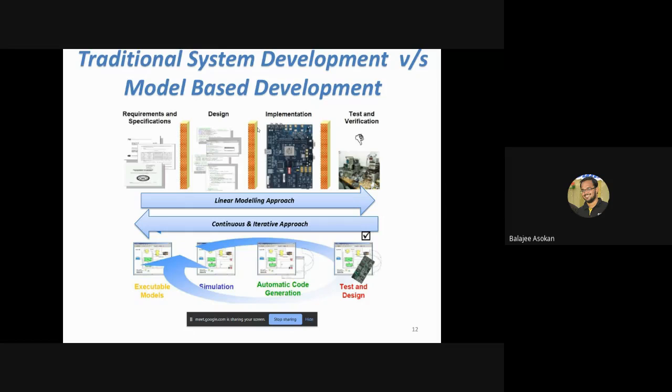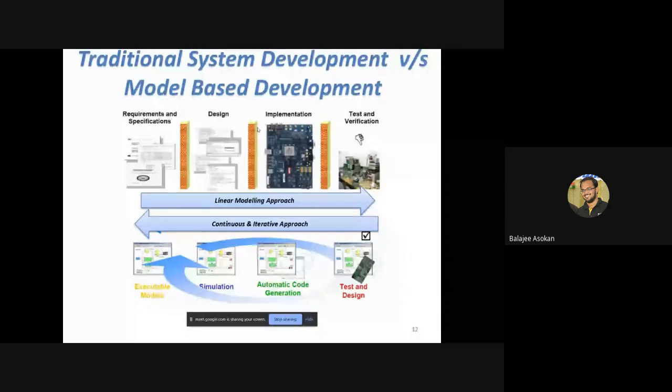See, basically there are two different models. For MIL testing, you will have the final Simulink model. You will take the top level subsystem, and it will have a defined set of inputs and outputs. You run MIL testing. When it does not give the expected result, we identify that there is a design error the developer has made.